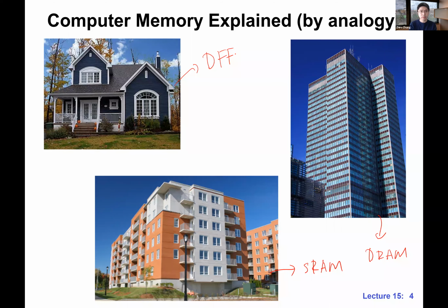Very good. So there's the addressing part, and there's this big decoder in front of these cells. There's a cell array that makes things slower, and of course, there are other things as well. Like for DRAM, you actually need to multiplex the addresses. There's a refresh and all of that. With DFF, it is much easier to access. Also, for multi-bit DFF, it's called a register. Many of you already mentioned this, and we're going to be looking at registers a lot today in this lecture.